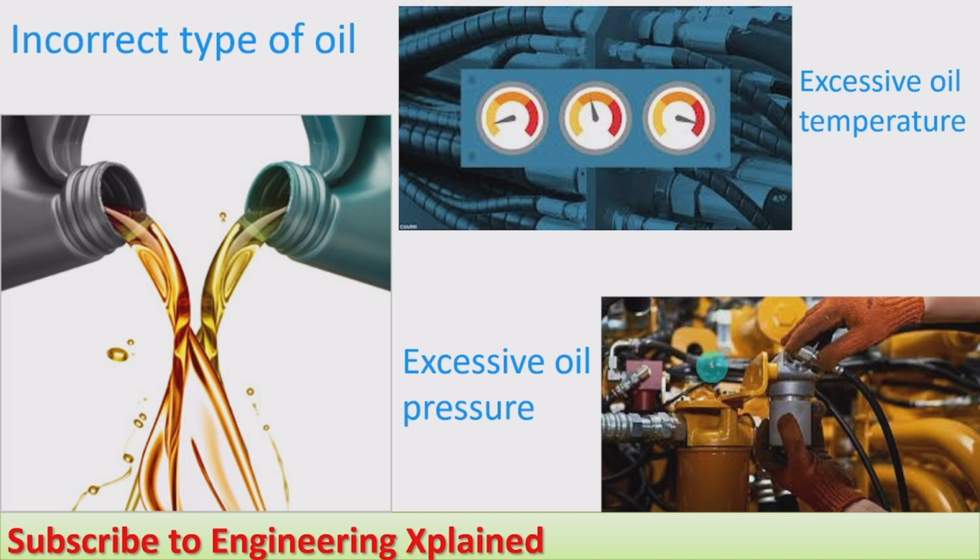If it functions properly, it will release that pressure and oil will be supplied to the tank. And if that pressure relief valve itself is not properly functioning, during that time excessive oil pressure will develop in the system, and that pressure will cause damage to the system.